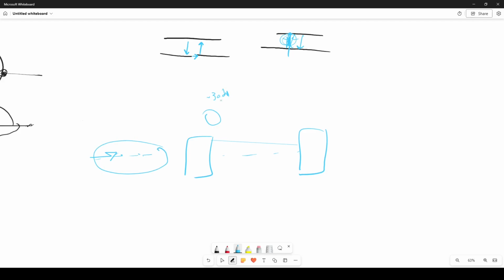And that's why the cross polarization generally is the most important in antenna arrays, especially if you have a dual pole antenna or something. That's why I was interested to show both, and to show when you choose this and when you choose this in terms of radiation pattern and back radiation. So if you clean the cross pole, you have to be careful of the back radiation because of the slot, right?